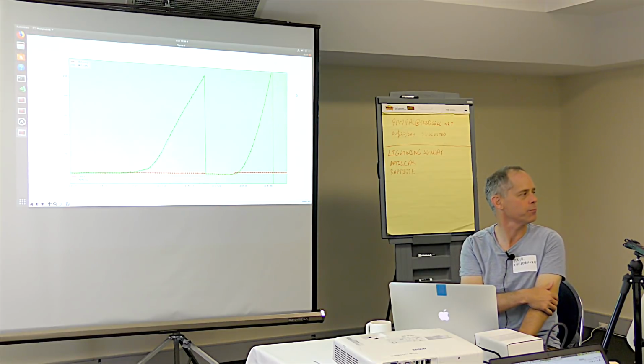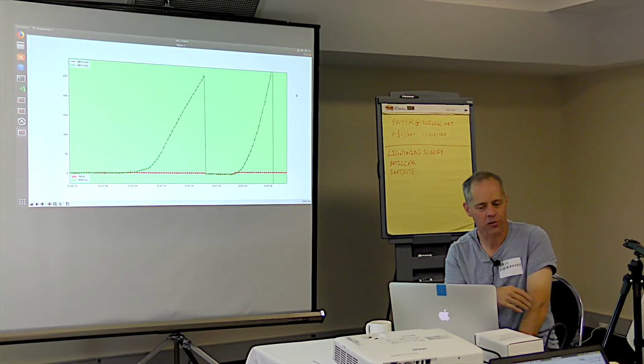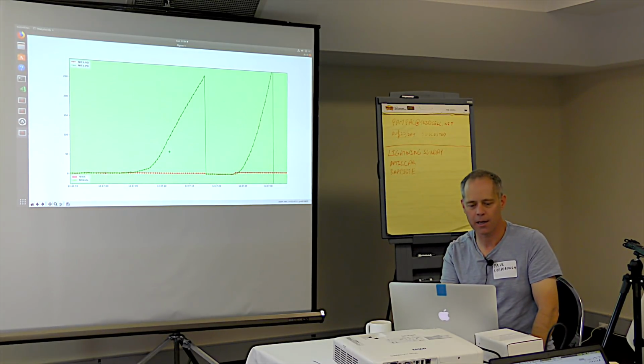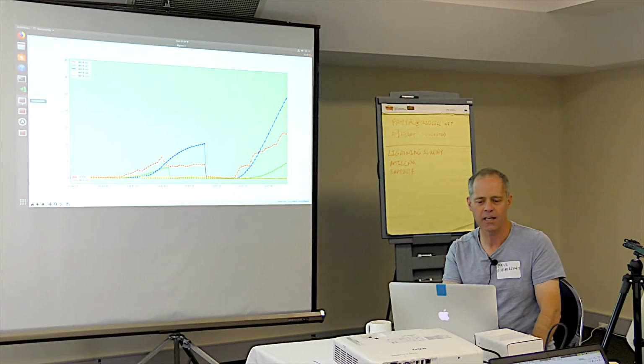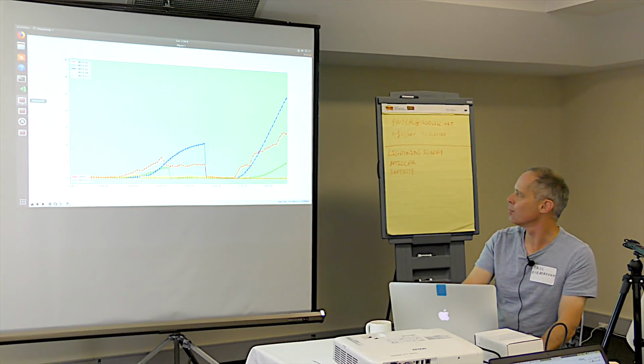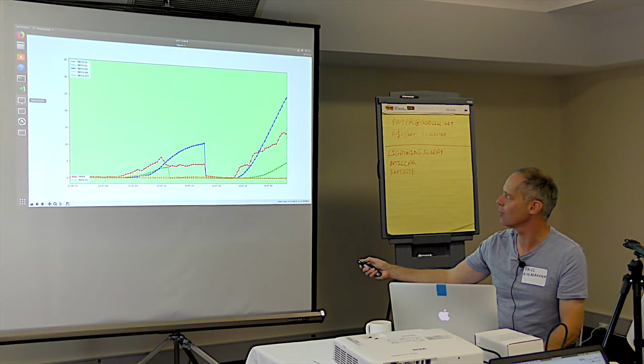Paul, is there any way of telling what sensors are no longer being fused? Yes. A couple of ways to tell. One is that if you looked at the normalized innovations, which are these NKF4, so you'll see NKF4.SV.